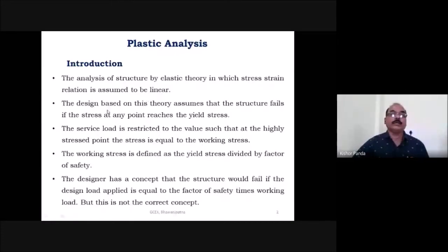The design based on this theory assumes that the structure fails if the stress at any point reaches the yield stress. The service load is restricted to the values of that at the highly stressed point. The stress is equal to the working stress. The working stress is defined as the yield stress divided by the factor of safety. The designer has a concept that the structure would fail if the design load applied is equal to the factor of safety times the working load. But this is not the correct concept.